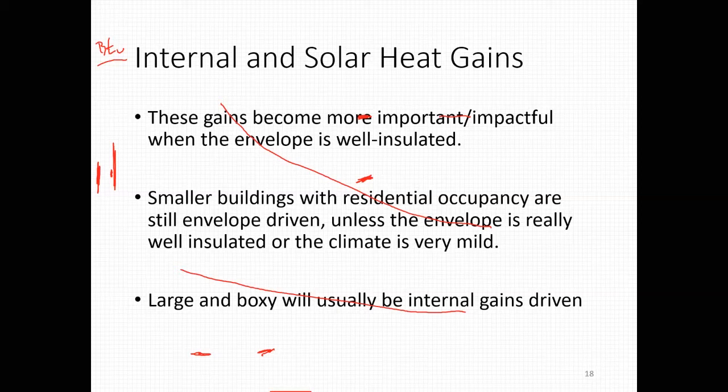In the climate zone he was in, he said you hit that point of diminishing returns at a foot of insulation, or about 10 inches of exterior insulation in the perfect wall that we'll look at later. Think about the implications of 10 inches of rigid insulation. You have to attach your cladding, your facade, to the structure of the building, so you have to go through 10 inches of rigid insulation.